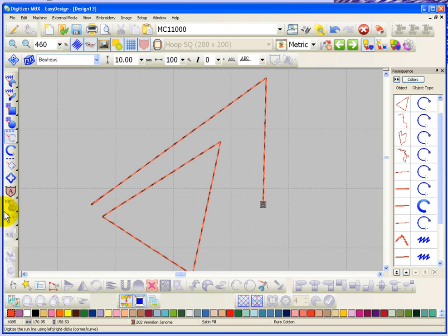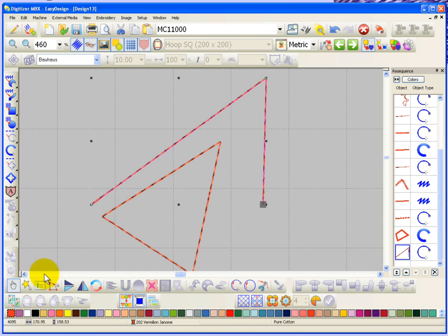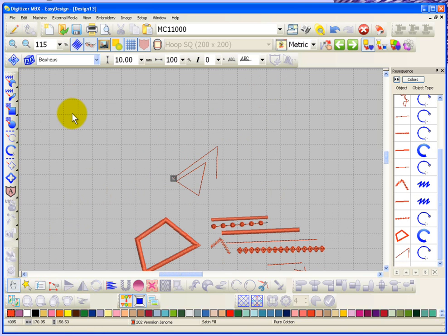and show that if I select Reshape on that open line, I can move the starting point, but not the exit point. So I can have it start in any place that I want to, but it's not necessarily going to adjust the exit point. It automatically updates that exit point to be where it seems to be the opposite side of the line from your starting point. So that's Reshape when you talk about line stitches. And so that's how to use the open line and the closed line, satin line, closed satin line, and how to select and reshape those objects as well.